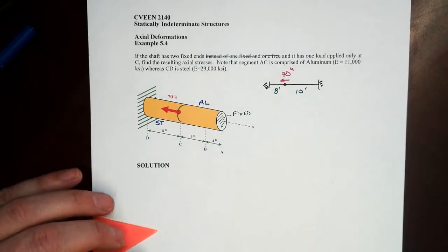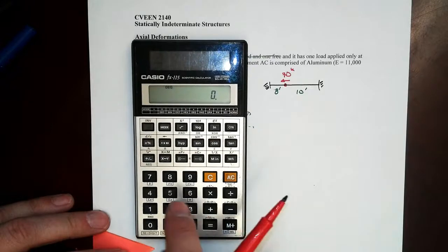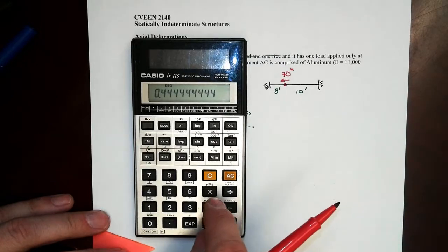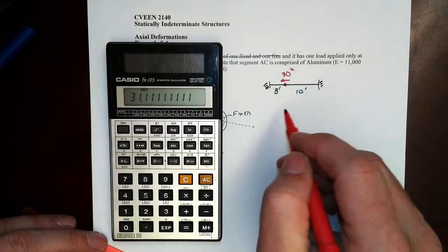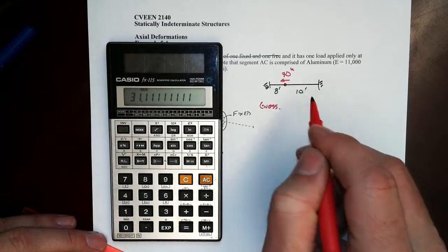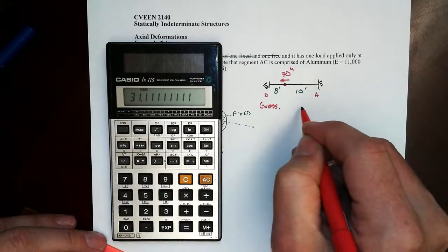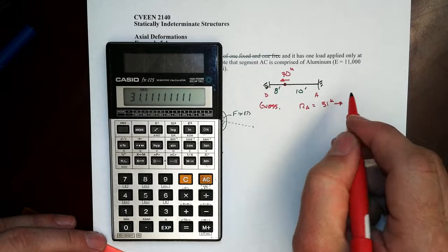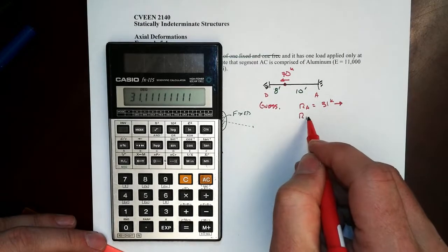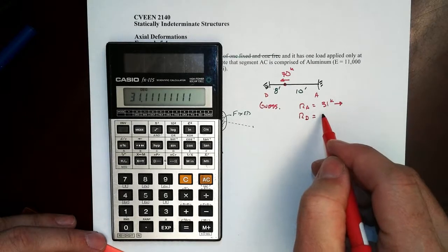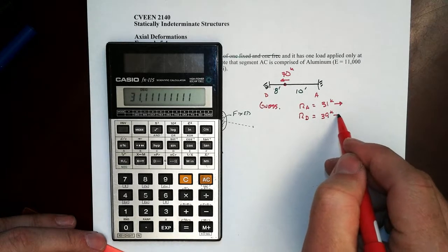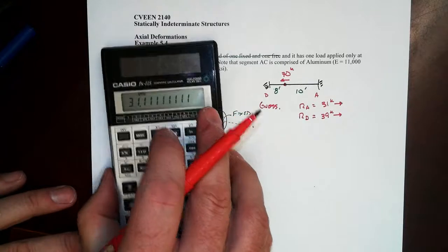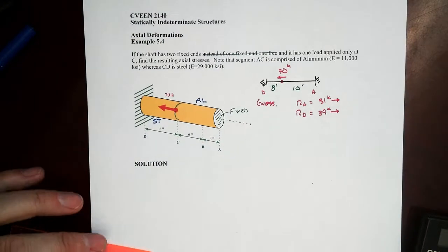I'm going to use that as my rationale that 8 out of 18 of it goes to the softer side over here. That'd be 0.4444 times 70. So that's going to be my guess. This is A over here, this is D. I'm going to guess that RA is equal to 31 kips acting to the right, because the load is acting to the left, and that would leave the balance over here at D, 39 kips, also acting to the right. Sum those up, that's 70 opposing the load. Pure guess, based on almost determinate analysis rather than indeterminate analysis.